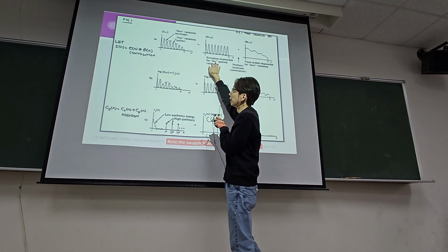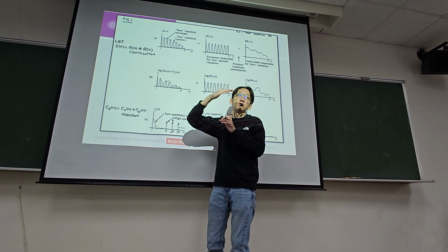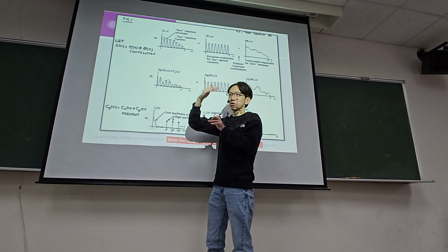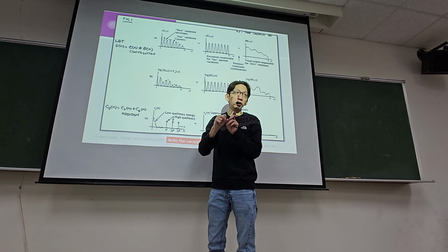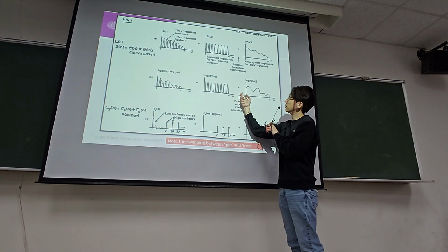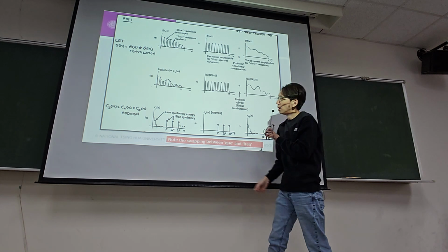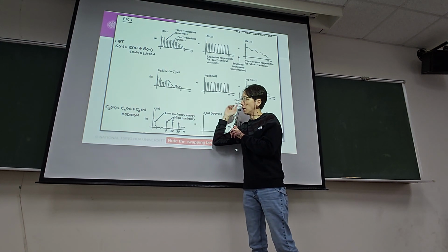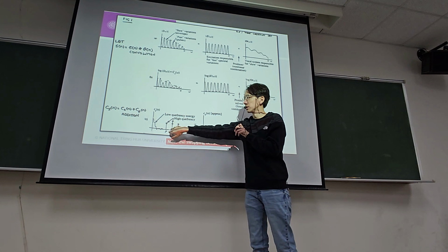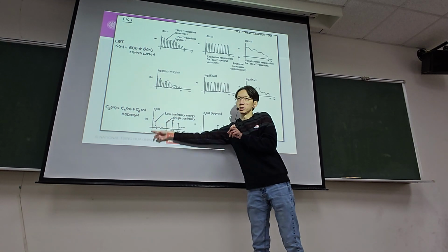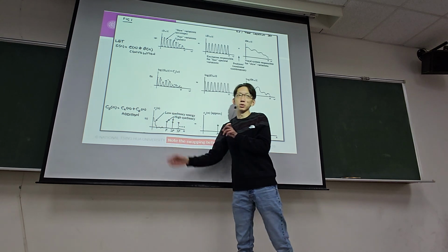Taking the log, the values shrink a little, and the original multiplication becomes a summation. Now you take another inverse transform, and the highly varying part will land here and the slowly varying part will land here, and then you can properly get the parts you want.